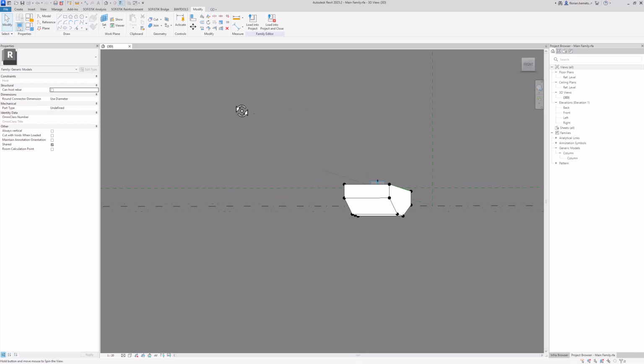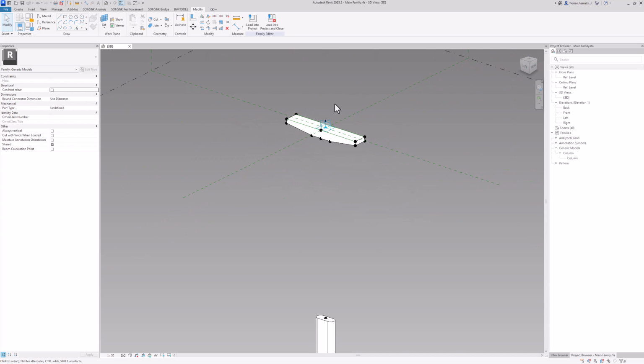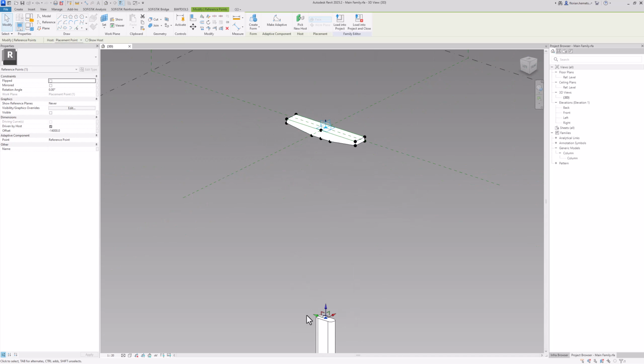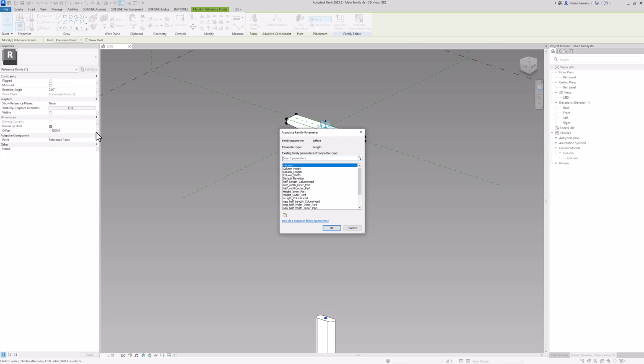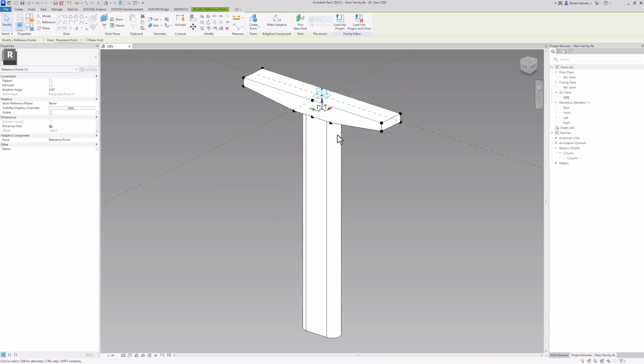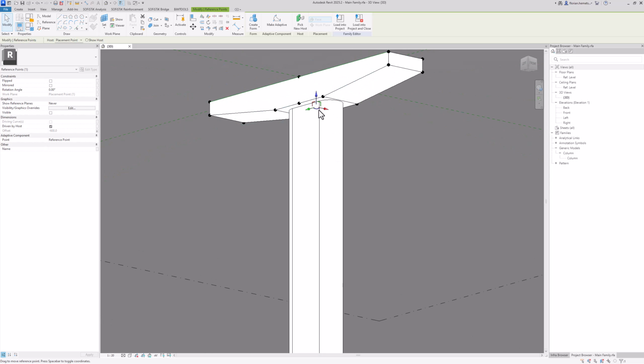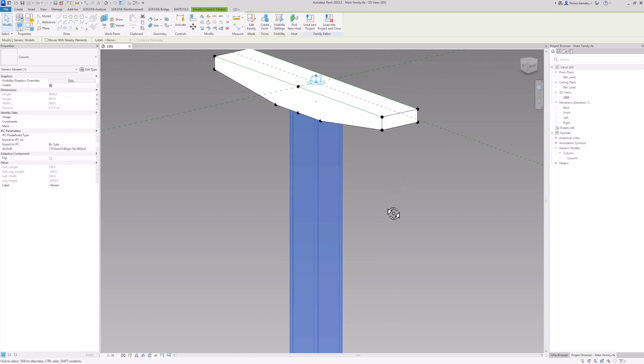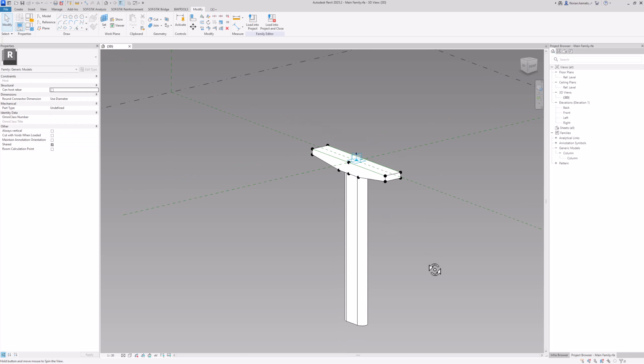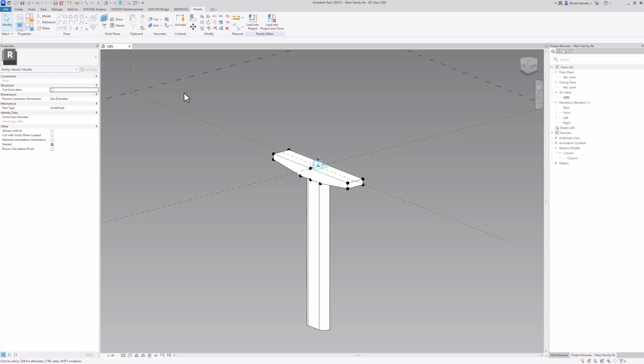The only thing left to create our T column is to now assign the proper height to the offset of our column top, which is the negative height of our inner part. Once I select it, everything is perfectly aligned. So far so good. This is all that is necessary to create a nested column family like this one.